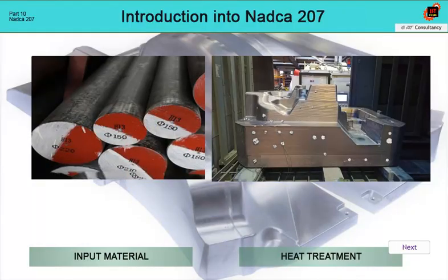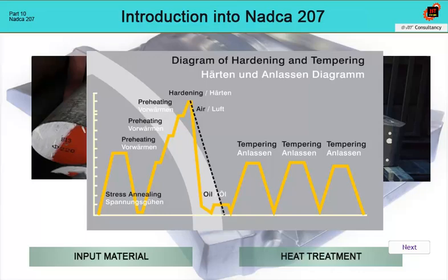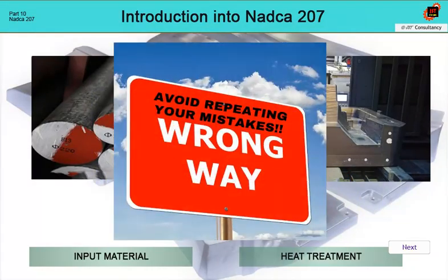Heat treatment is another important step in the production of die casting tools and has its own rules, which must not only be observed, but also controlled. However, it must be taken into account that the aim of the heat treatment is to maintain the purchased properties of the material. No heat treatment can improve them, but it can make them significantly worse. It is therefore important to have a reliable supplier with highly specialized knowledge for this operation, but at the same time, it is necessary to control this supplier.